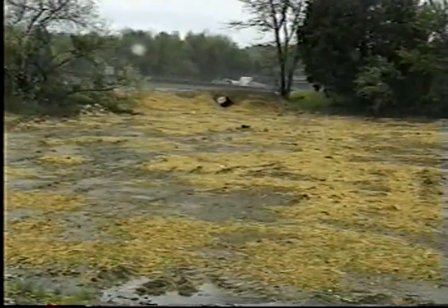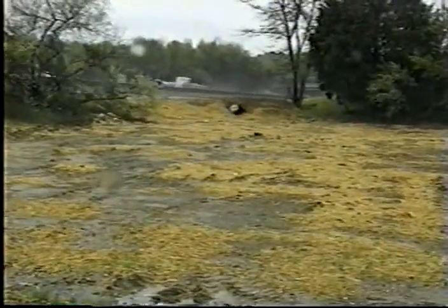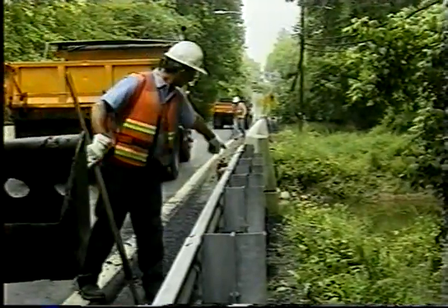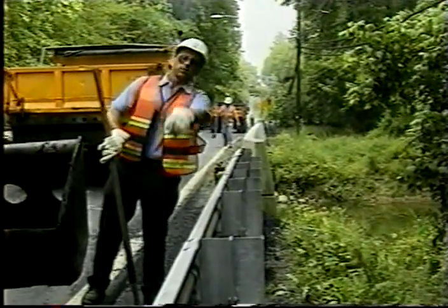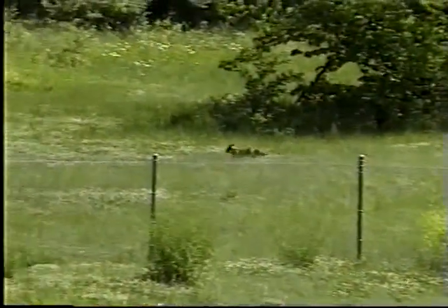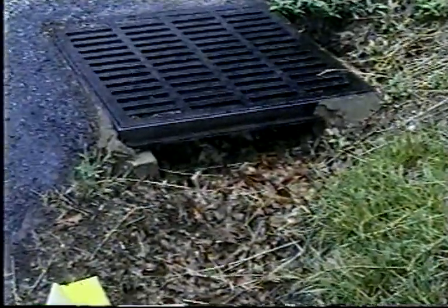To keep the design functioning, perform both routine and preventive maintenance on the pavement surface and its drainage system, ditches and channels, drainage structures and slopes. Any work that is performed must be done in accordance with established procedures to reduce the effect such work may have on the environment in terms of sedimentation, turbidity, and toxicity. Some types of maintenance work can require personnel certified in correct procedures. Although the preservation of the road is the primary reason for performing maintenance, consider the potential for legal problems that could result from lack of maintenance of facilities or improper installation or design.